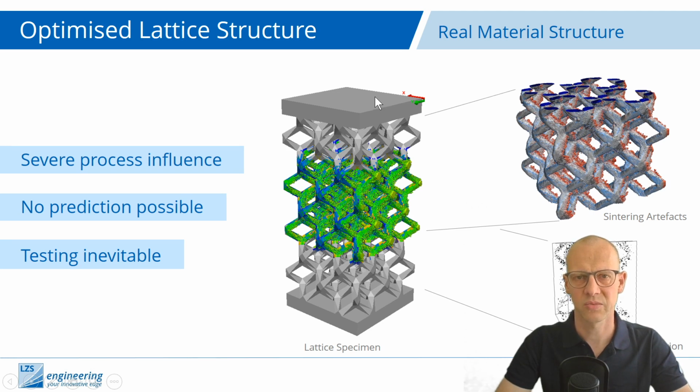This just results from when you melt your material with your laser, even if you have the fastest heat and cooling rates available on the market, the material is still a bit longer hot than you needed, and some powder lying aside or beneath your focus point will get melted and stick to the material itself.